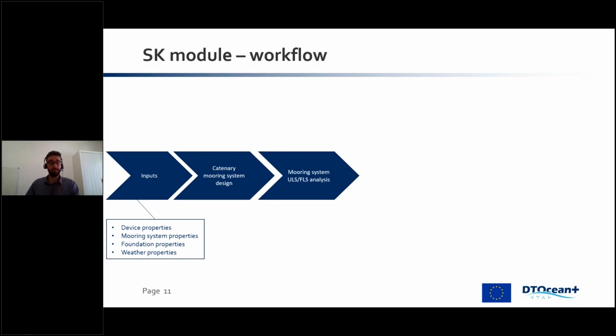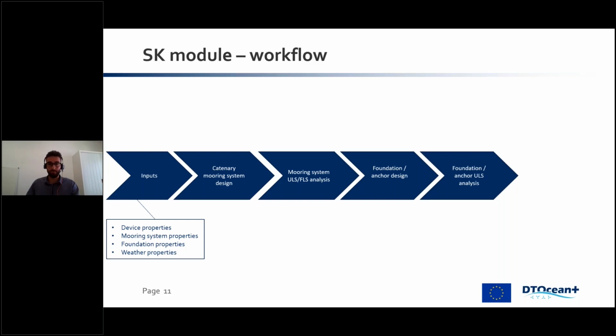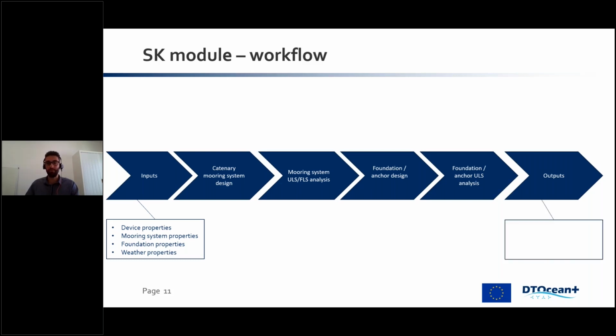If the user has defined a mooring system, the mooring system is analyzed based on ULS analysis and FLS analysis if required. Then the foundation and anchor design is performed if chosen by the user, and then these foundations or anchors are analyzed by computing the ULS criteria. And finally, outputs are written out of the module and displayed to the user.